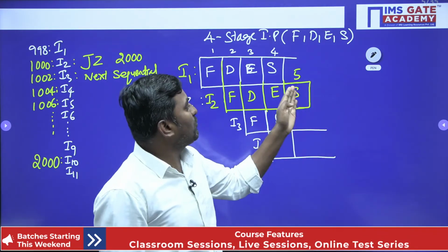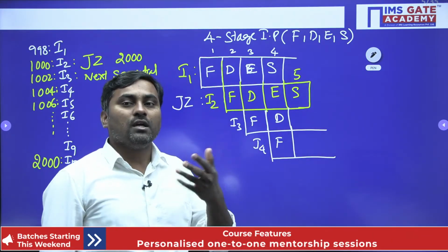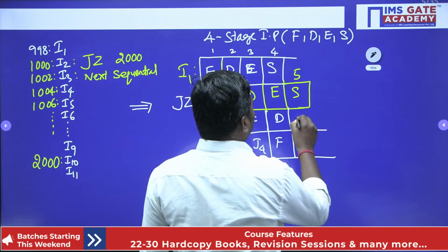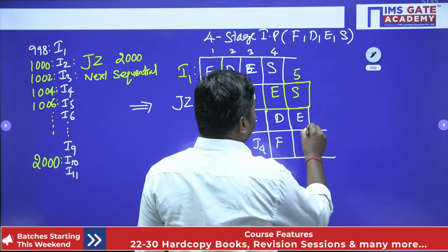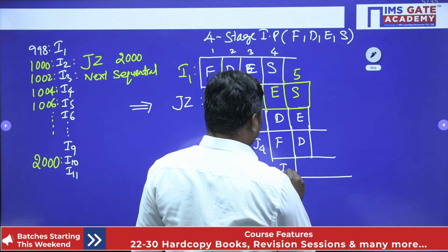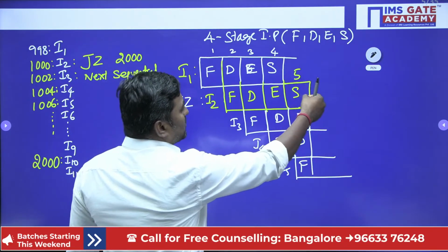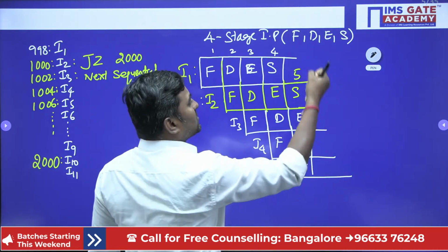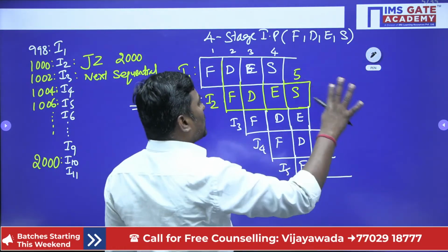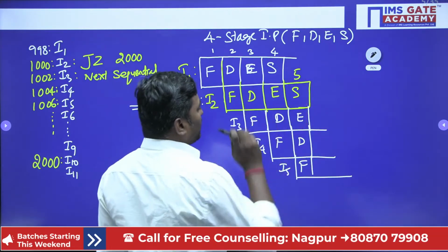But only at the end of the fifth clock will we give the address. We give the address of the target instruction based on the condition satisfied. When you are doing this, this instruction has already started executing, this stage is free, the other instruction is decoding. Now another instruction, I5, also got fetched. If the condition is not satisfied, you have to fetch the next sequential instruction; we will only come to know at the end of the fifth clock.